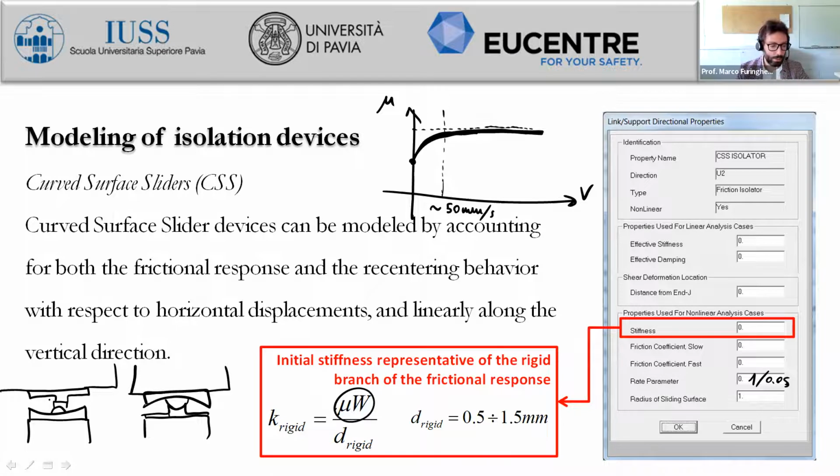Okay, so here we have the vertical force, which is aligned with respect to the hinge, so it will not change the position with respect to the top plate. But in the second case, it will not change the position with respect to the foundation, to the substructure, and it will represent the P delta effect on the superstructure.